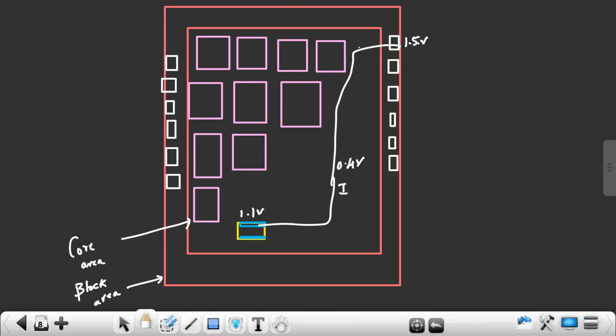And this metal layer is also having what? Resistance. So resistance and current will form what? Voltage. It depends upon what is the resistance, and how much current is flowing. Based on that, this IR is going to give me what? Voltage drop on the metal layer. And that voltage drop will convert in the form of heat.